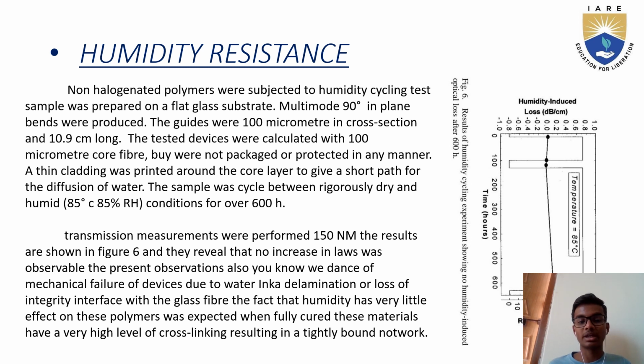The sample was cycled between rigorously dry and humid, 85 degrees Celsius and 85% RH, conditions for over 600 hours. Transmission measurements were performed at 1550 nm. The results are shown in figure 6 and they reveal that no increase in loss was observable.